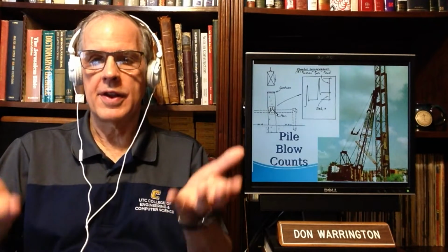That's not very efficient. But people began to put the pieces together and realize that if you understand what kind of impact force goes into the pile, and then you see the set that comes back, the lowering of the set and the increase of the driving resistance are related to each other.